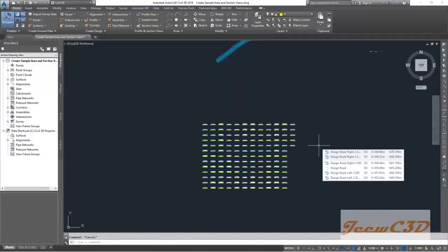You have to follow the design concept which I told you in the earlier lecture series: how to select things, how to do the trial alignments, how to apply the super elevation and select the curve radius, how to cope with the constraints. All these things you have to consider when you are designing the road, rather than just drawing a line or curve in the Civil 3D software, and that is not highway design.